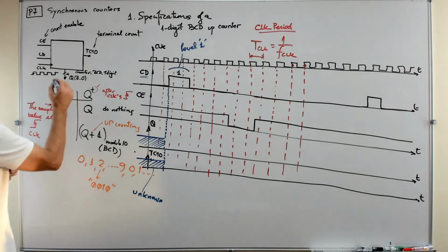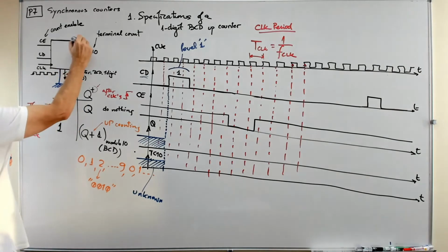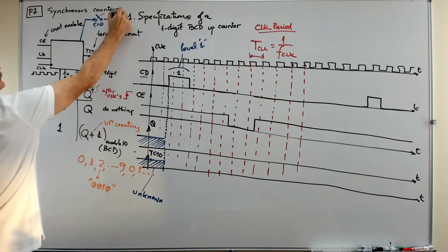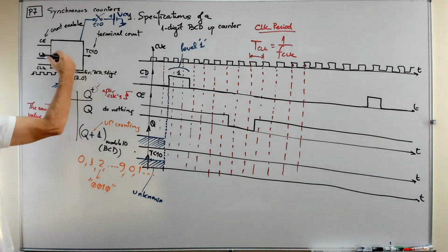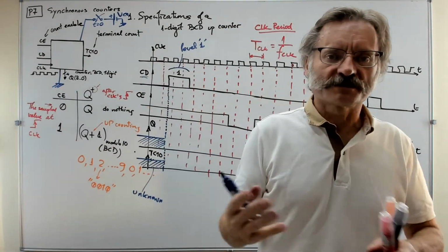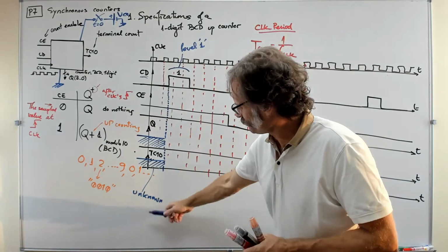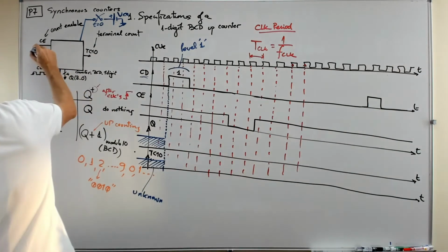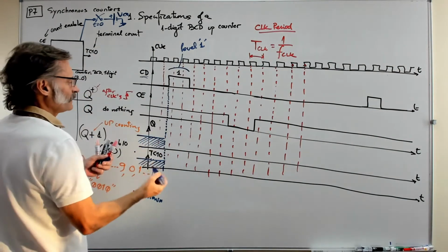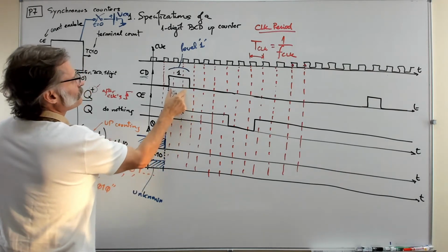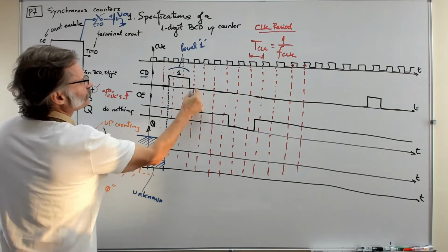You never know what is happening when you connect the power supply to the system, you see. You are switching on at t equals 0 the battery to the system, VCC, and now when you connect the battery, the system sets itself to some value of ones and zeros, but so it is undetermined. You know nothing about this initial value. But when you click clear direct, just driving a single pulse, now the machine is settled very well, so the Q goes down to 0. So at least meanwhile you have a 1, and up to the next rising edge.